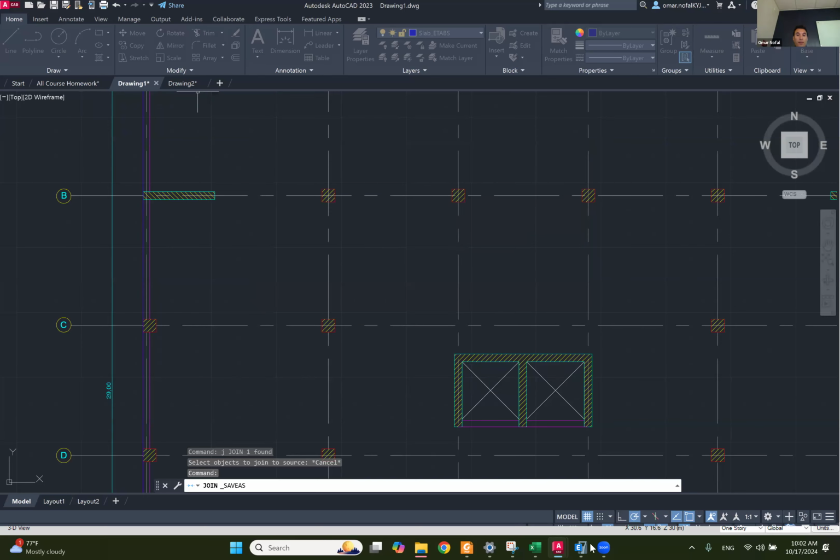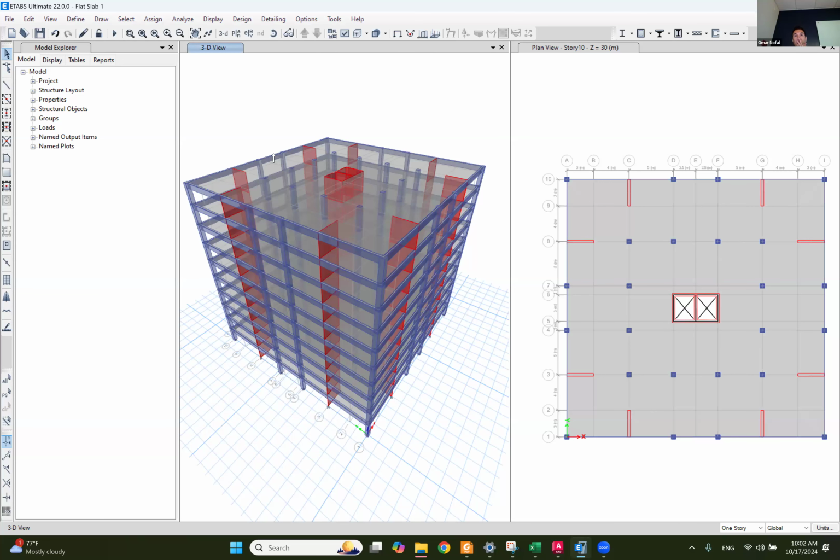All right, so I'm here. Okay. Let me tell you something. I can close this window and open a completely new window, like I can start from scratch. But what is going to happen is I'm going to bring my drawing, and when I tell the software, this is the layer of columns, assign columns at this location, the software is going to use the default material, create a cross section, and then put it on your drawing automatically.